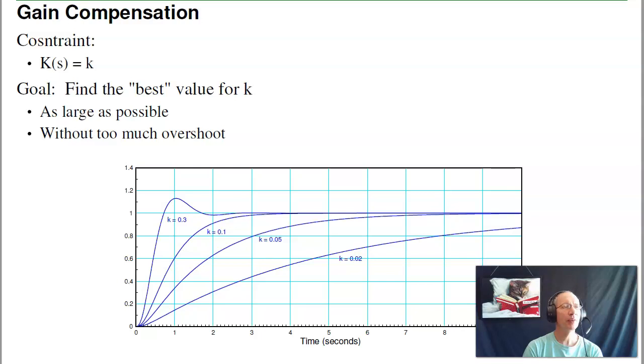Now in the previous lectures we looked at root locus plots. With the root locus, the poles shift as I change the feedback gain, and I can see from the root locus plot how it's going to behave. For example, if I increase k, I can go from a pole which is on the real axis, start shifting left, speeding it up, then it becomes complex.